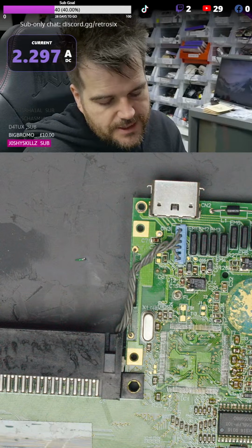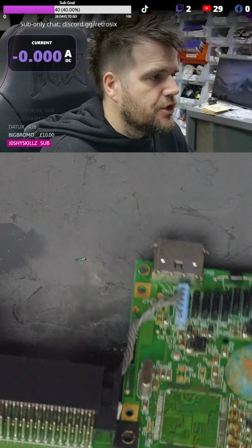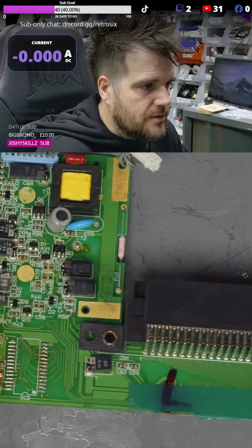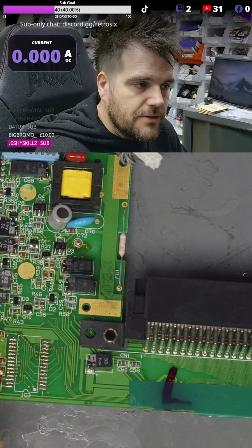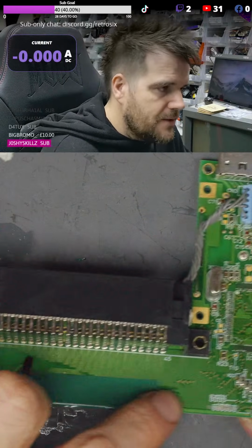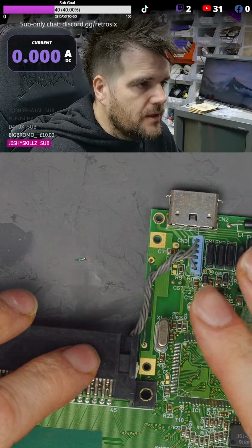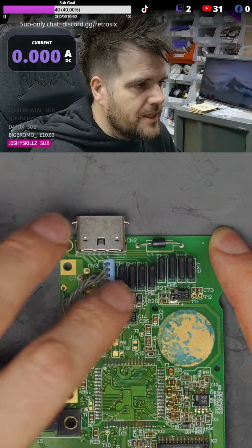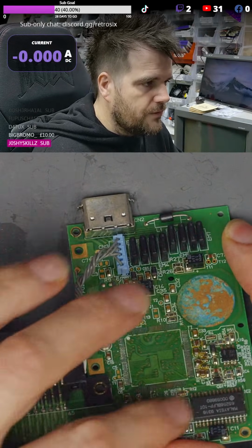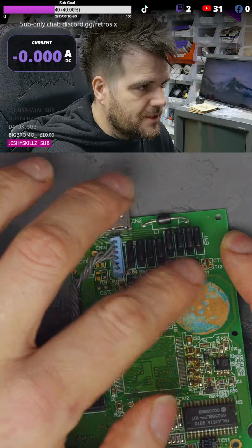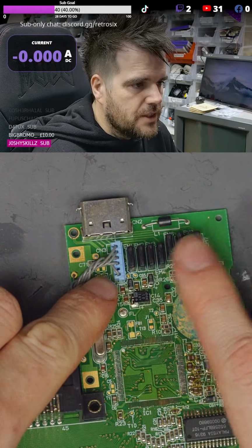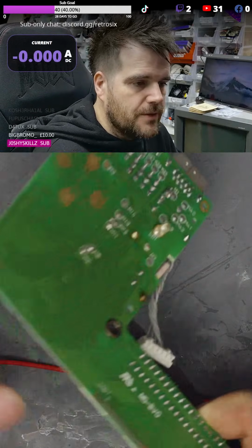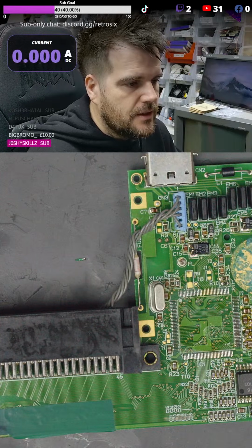If you wanted to find a dead short, you're pretty much at the point of finding out what trace it's on, by injecting 1 volt typically into certain areas until you find that that area gets warm, finding where the thermal will take you to, and then once you get to as close as you can, we know it's got to be somewhere around here because something's pulling all of the trace of the circuit hot up until this point. So the dead short is located around here, and then you'd really focus your search around this area. That's how you'd basically do it.